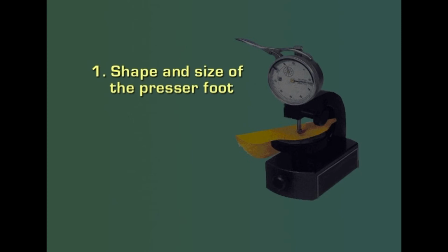Several points require consideration in the practical application of this principle, and in this, the shape and size of the pressure foot. So, a circular foot is usually used, a common diameter being 3/8 inch, but this may differ if desired. The ratio of the foot diameter to the cloth thickness should be not less than 5:1.